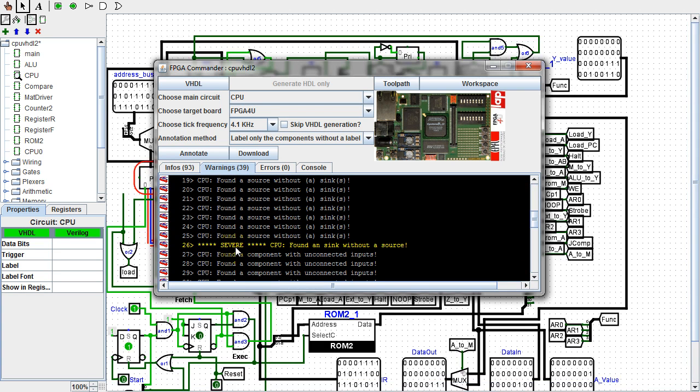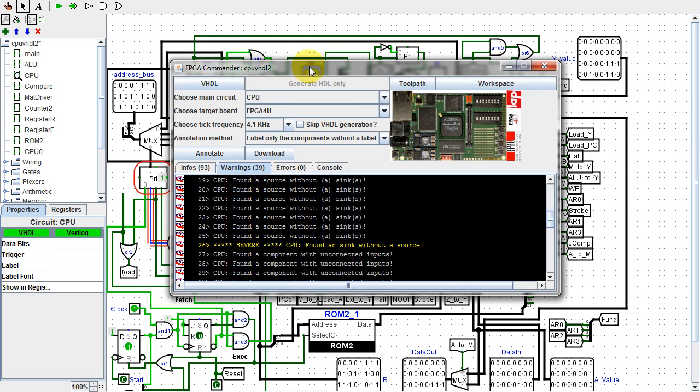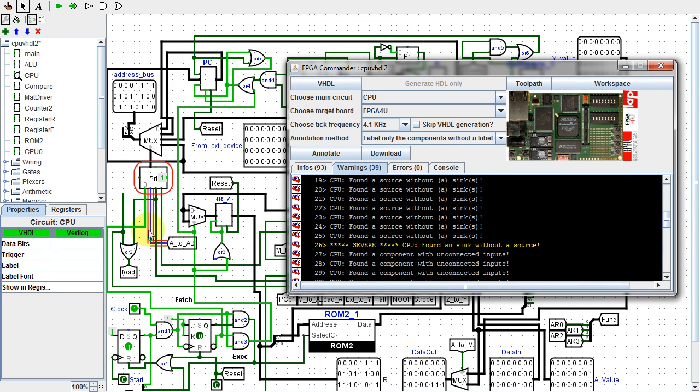This warning is a good one to heed. Since this particular line wasn't needed because I never did get that instruction to work, I never connected it to anything. I later discovered my VHDL design didn't work correctly because of that line, so I can either take it out here, replacing it with a constant 0 and rerunning the conversion, or I can fix it in the VHDL code. I think I'll fix it in the code later.